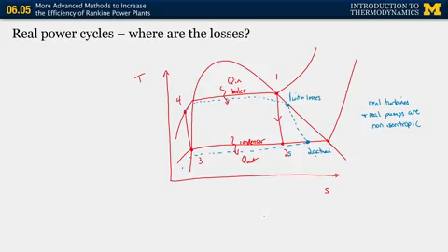Because at that point, you're going to potentially have ambient gases leak into the system. So this is probably limited by the ambient pressure. So you'd run your condenser at slightly above atmospheric conditions. Okay. And then again, we're going to target that the exit condition has to be a fully saturated liquid.